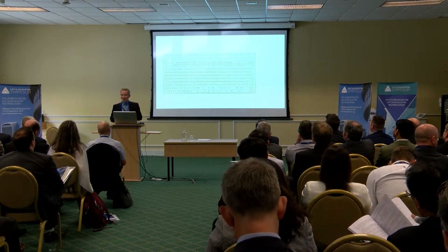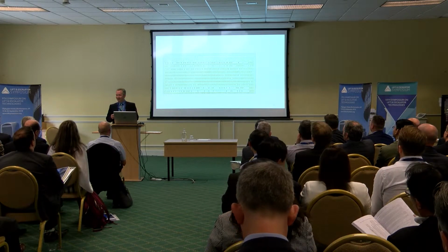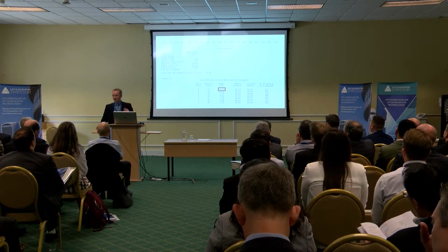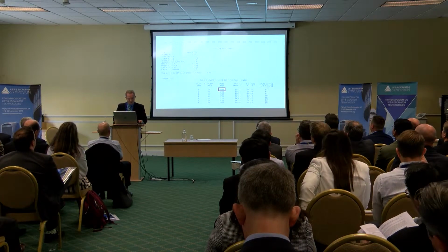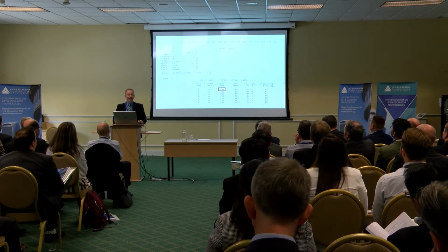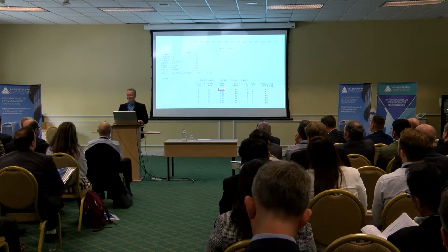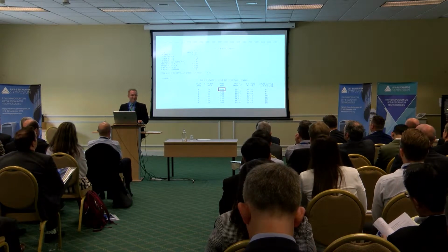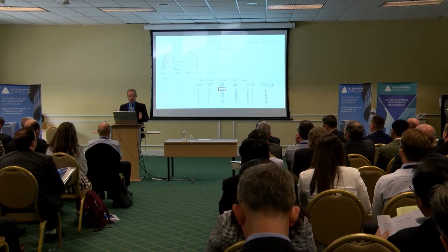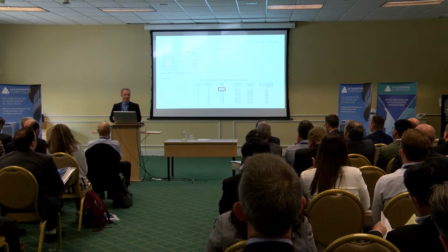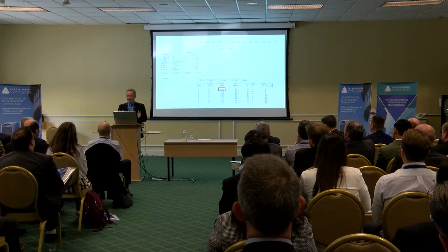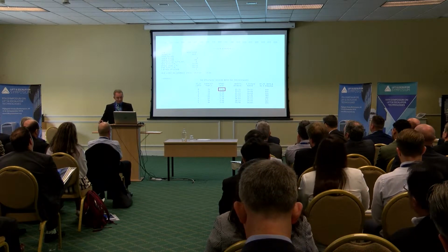But that actually was a sort of simple expert system, and you inputted all the data and it gave you an answer. I've highlighted one of the results here. This is a high-rise office block where you've got a 1 meter per second lift. So it's done the calculation, but it really isn't an expert. Yeah, so it does include some sensible answers in the result, but it isn't an expert because it hasn't realised that actually it's not just interval and handling capacity. It's called 5-minute ratio and waiting interval, but those are what they are. It doesn't just include those. It's actually to do with travel time as well.